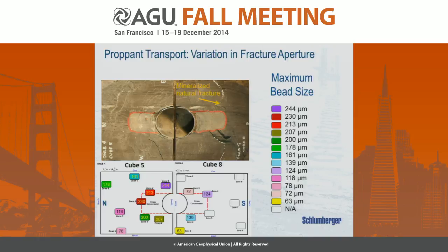It means that we created some hydraulic fracture propagating a few inches from the slot, but there was no opening, because we have evidence that opening in the opposite direction was significantly higher than in the direction where we have a mineralized interface. And therefore, we assume that this mineralized interface arrested fracture propagation and restricted fracture opening in the other direction.